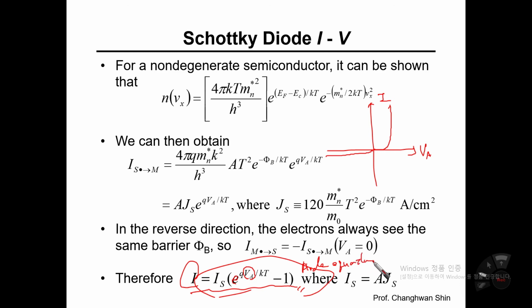From the lectures today, you should draw the energy band diagram when the MS diode is forward biased and reverse biased, and you should physically explain how the current flow is exponentially increased when the forward bias is linearly increased. On the other hand, when the reverse bias is linearly increased, the total amount of current flow across the MS diode is quite constant and very minimal.